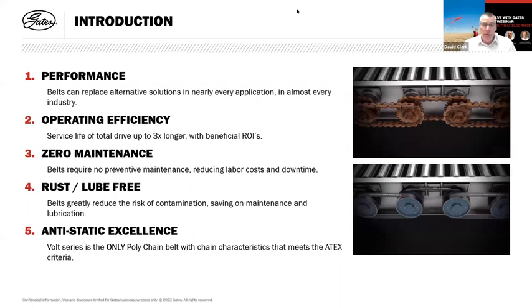Belts are inherently efficient. We're mainly talking synchronous belts here because those are the ones which are most likely to replace alternative solutions. You can get a high efficiency drive, and one of the big advantages of belts is that efficiency is steady throughout its life. So the efficiency you have at the beginning of a drive, which could be in the high 90s on a well-designed drive, will be consistent throughout its lifetime with either minimal or no intervention to keep it so.